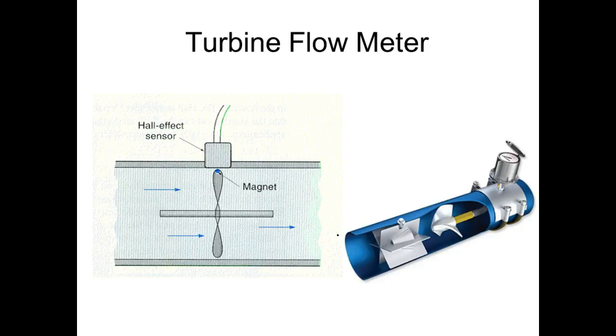So this works almost a lot like a paddle wheel, where we put a magnet on one blade, right? You understand? And then we have the Hall effect sensor, and every time the magnet comes flying around, it gives us the pulse, and the rate of the pulse is in direct proportion to the speed. I was looking at the picture. Oh, okay, that's the magnet.